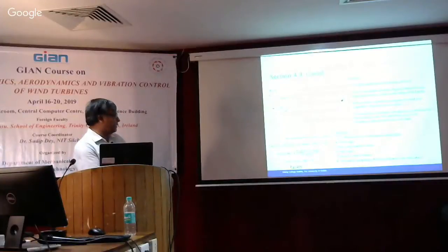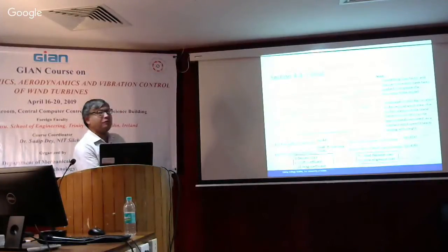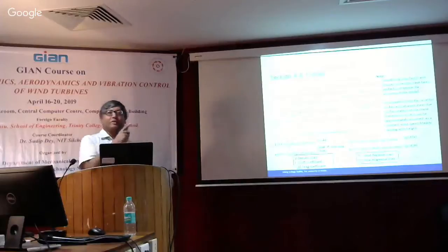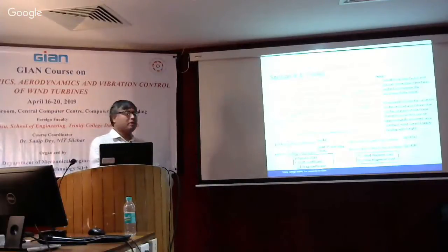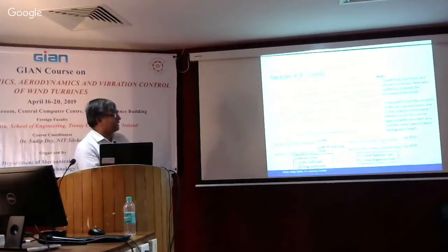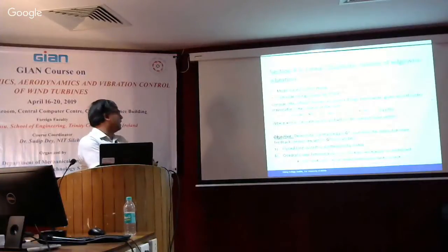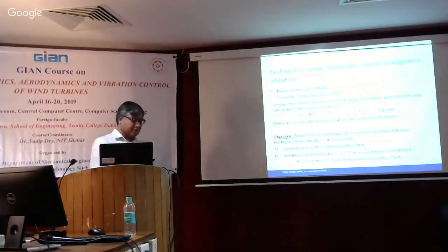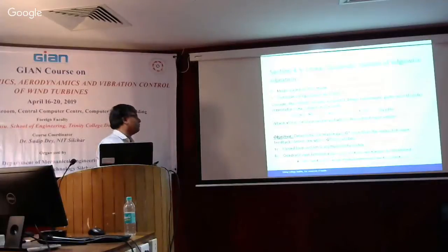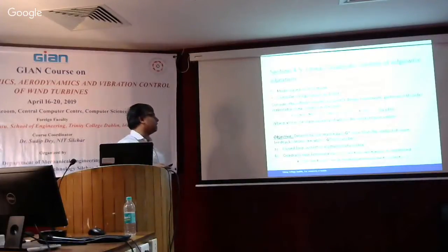That has to be properly accounted for, but that comes from the original equations we derived this morning in terms of the partial derivatives. The load from the wind will follow the exact same procedure that we discussed, so I'm not going to discuss this once again, but with appropriate corrections and so on, like the Prandtl tip loss correction. Here we did a study based on only the first mode shape of the blades and the tower, so basically a 4-degree of freedom system.